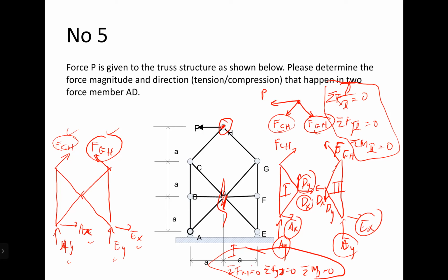So it is the action and reaction happening at point D. When you join it together, DX and DY will not be there because they cancel each other out. DX and DY from the left one and DX and DY from the right one are in opposite directions because it's action and reaction. That's why when you join both systems, they will be gone. There is no DX and DY here.